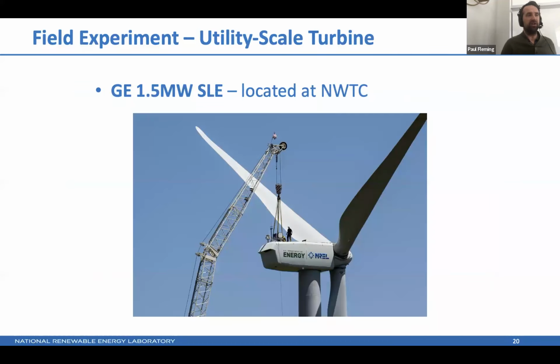We basically ran this experiment toggling every hour. So every hour we would either be in the baseline mode, where the turbine was commanded to operate normally, or we'd be in the controlled mode, where it was given this optimal yaw offset.